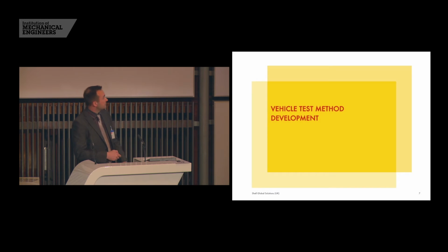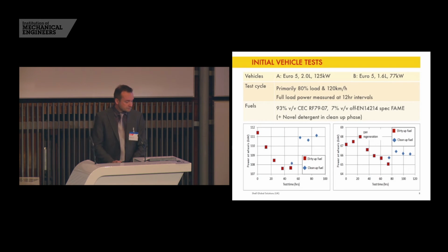So, overview of the test method development. We ran initial tests with 2 Euro 5 vehicles and applied a test cycle which was primarily 80% load and 120 kilometres an hour. We measured full load power at 12-hour intervals to determine deposit formation.